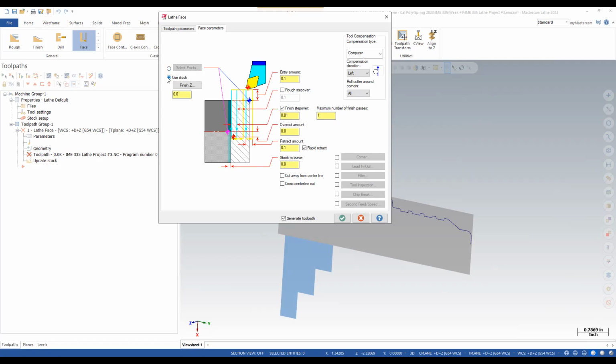Now, what I want to do is leave 5 thou because this isn't the finish tool. So where this says stock to leave, we're going to leave just 5 thou. We're going to come around with the other tool and finish all in one. Sound good? But we're going to get rid of 20 thou and kind of qualify the stock. Make sure your pullout was decent. If it doesn't face anything, you didn't pull it out far enough. If it takes a huge cut, you pulled it out way too far. Fair enough, you didn't use the gauge right.